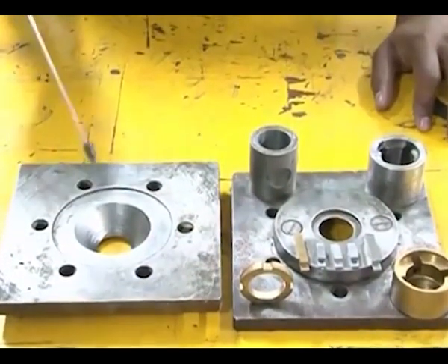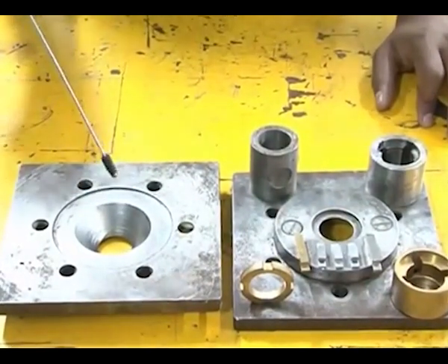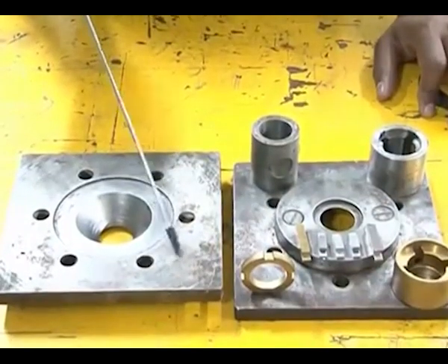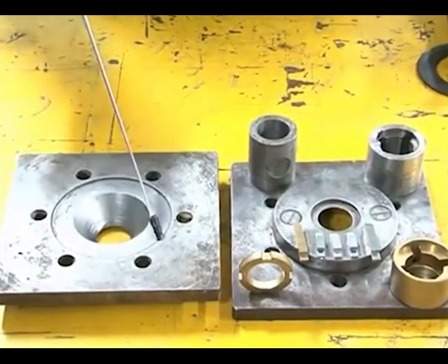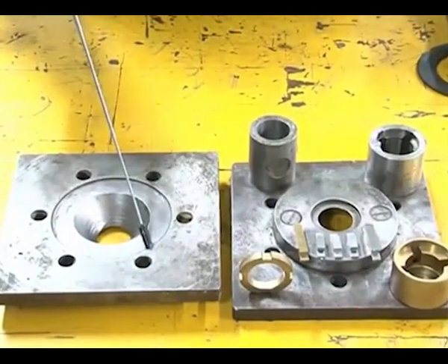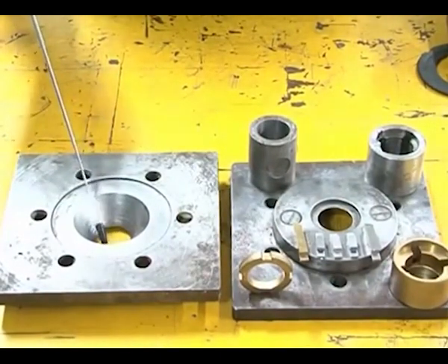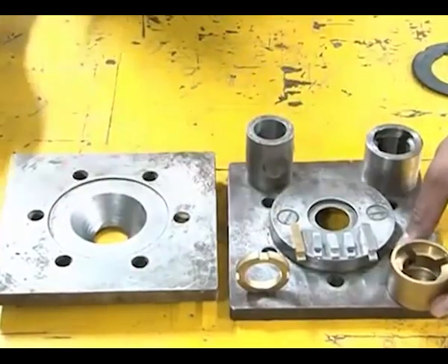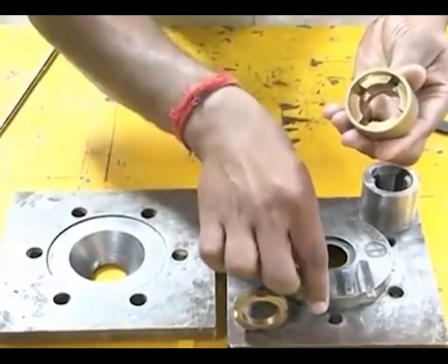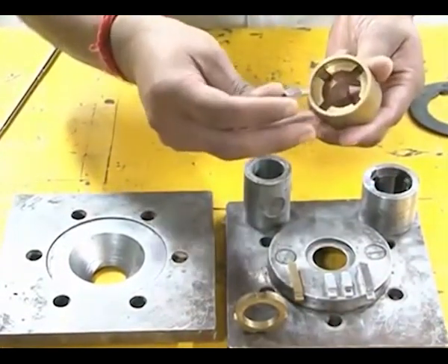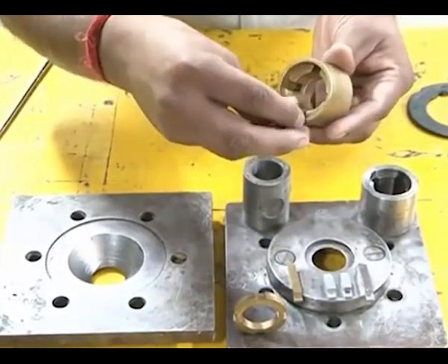Tooling controls the flow of the medium in the place where it is required. So this is the bottom plate and this is the top plate, and this diameter size is equivalent to the lower medium cylinder size, and we have a taper portion to control the medium gradually into the working region. And this is the work fixture where you can fix the workpieces. These are the workpieces, and you can fix these workpieces like this.